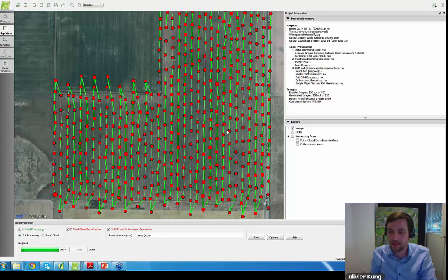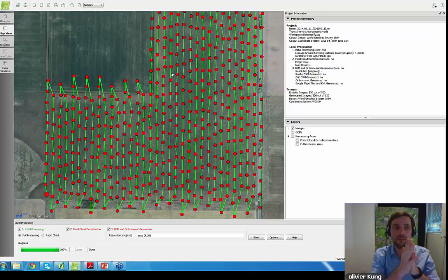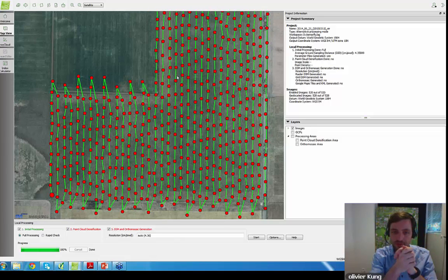So it's with the near infrared camera that they are selling, which is basically a normal Canon camera with a modified filter. In addition to just being this modified camera, it goes through the new workflow of the post processing software of SenseFly that allows to convert correctly the raw images into very good imagery that doesn't distort the radiometric values. So as input for this data set, the images are ones where the radiometry is not distorted, and that makes a huge improvement in the quality of the results.